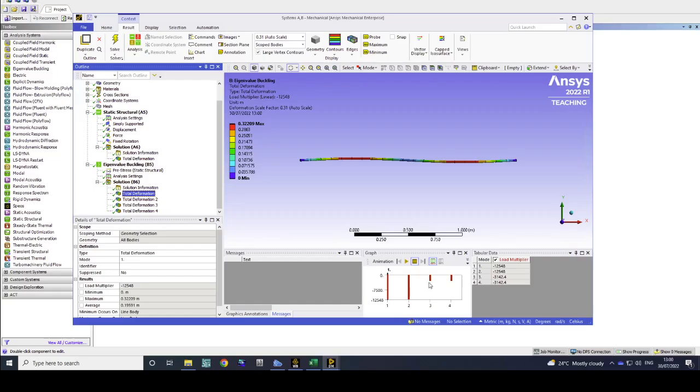But you know that buckling would happen under the smallest magnitude of the load. So essentially mode 3 and 4 are happening first, and then mode 1 and 2. This is the consequence of us defining the load in a positive direction, in tension. If we had put it in compression, these values would have been positive, and then mode 1 and 2 would start from 3,142.